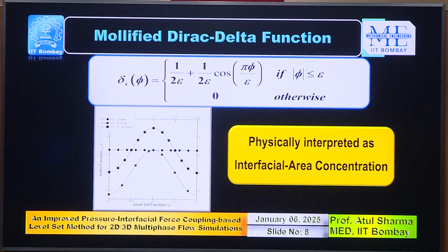although the idea was there for the last 5 years, we have used this physical interpretation to demonstrate in the formulation that in the diffuse interface method you can apply the surface tension as a surface force, and the results you will get will have very little mass error, and will be even more accurate than the sharp interface method.